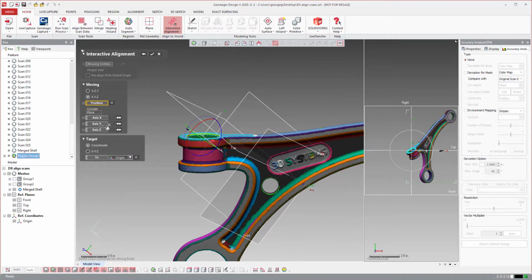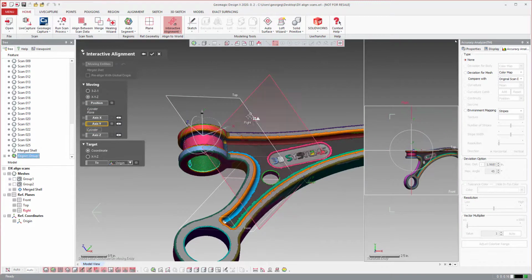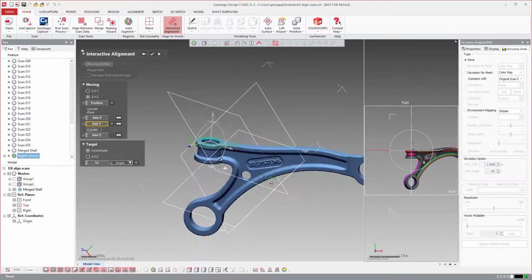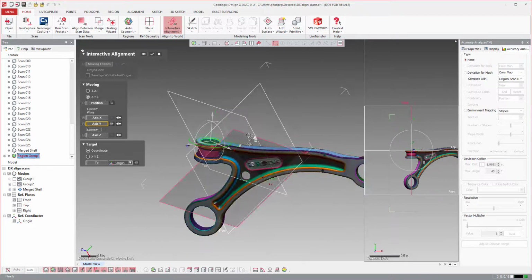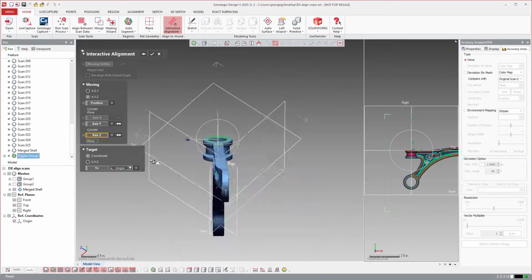I want to constrain that cylinder with the y-axis. So I can reuse that same cylinder and say I want to constrain that with y. Now, I could use this cylinder, I could constrain it with z. I could use that plane and constrain it with the z-axis because I could square that. That's actually a good way to do it. I could just say square the z-axis with that flat plane right there.